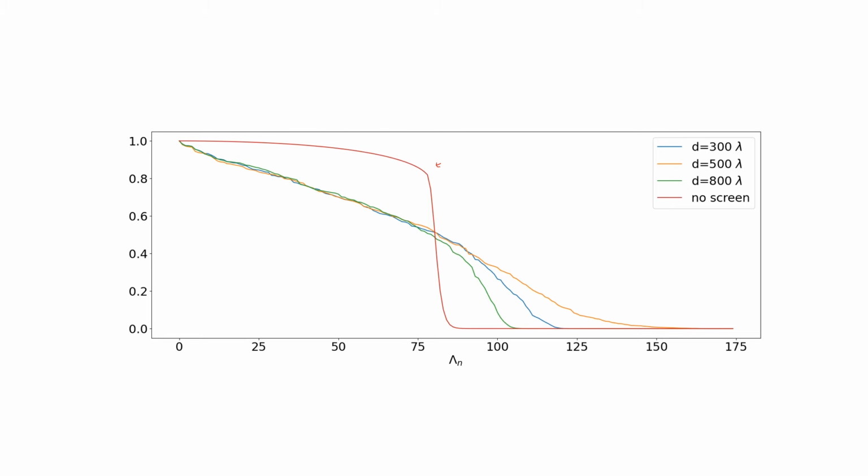So if we put the phase screen exactly at the input plane, that doesn't really change the modal structure of the signal that we would get through. We've already assumed that the input could be random, so multiplying the signal by a random phase screen doesn't change the sort of modal density that comes through.